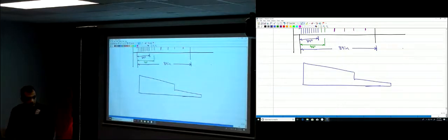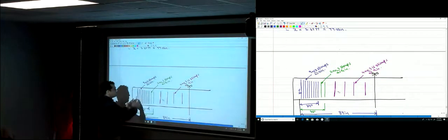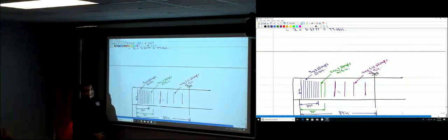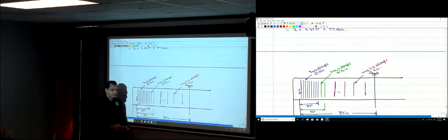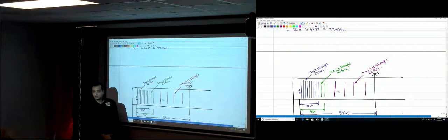Why did you use 6 and 9 inches? Does it matter? S equals 6 and S equals 9? No, you just want to increase the spacing. Here you need 4 inches, so you just need to increase it, maybe 6, 7, okay? You didn't have to provide 2 different spacings, by the way. So on the test, if there is a problem like this, I will ask you. If I don't ask you to change the spacing, just design this part, because providing 4 inches of spacing everywhere is a good design, right? It's not a bad design, but it's not economical, okay?